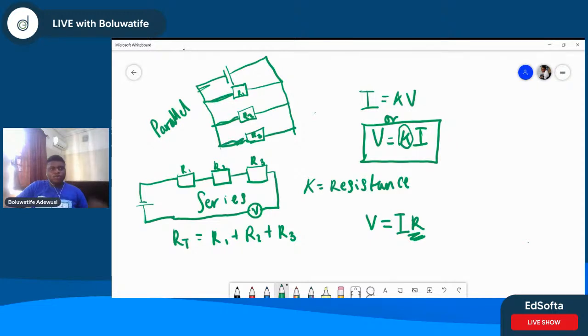Do you understand? So they are not... If I had a connection here, right? If I had a connection here, from here to here, then they would be in series. But because the resistors are not connected to each other in any way, they are independent. So that's why we say that they are parallel. So now the question: how do we know the total resistance of the circuit?